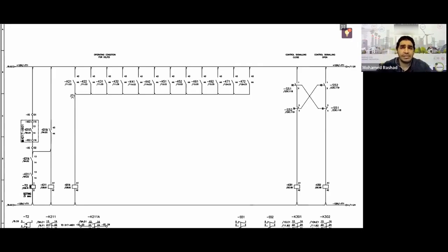I will activate a timer. The purpose of this timer is to start counting from the moment I give the close command to the disconnector or air switch. Ideally, if the disconnector or air switch completes its operation before the end of this time, then everything is fine. If it takes longer than this time, as soon as the timer finishes, it must give me an alarm and perform a specific action.